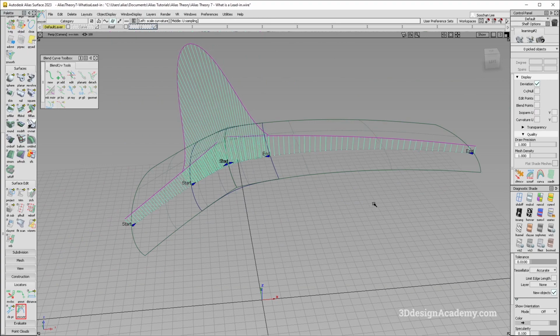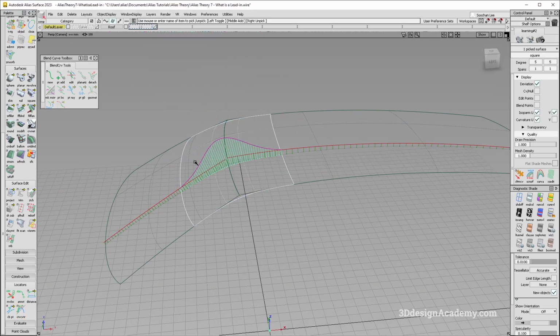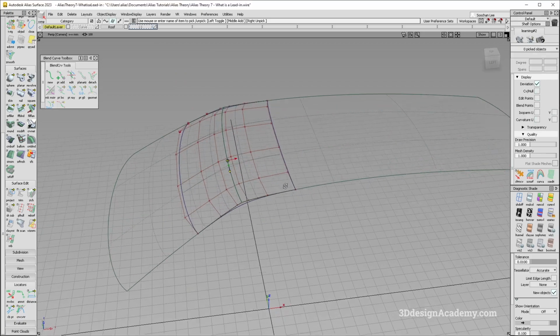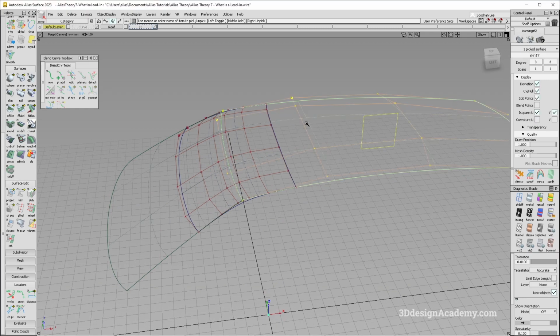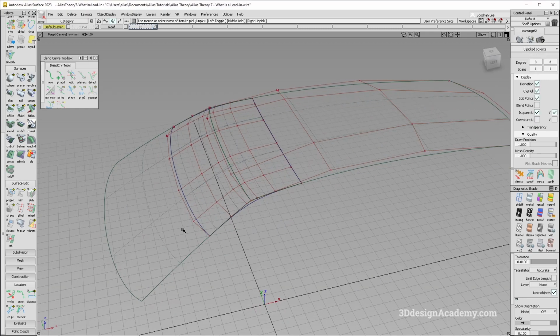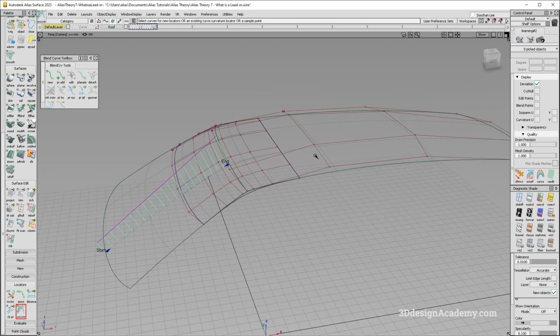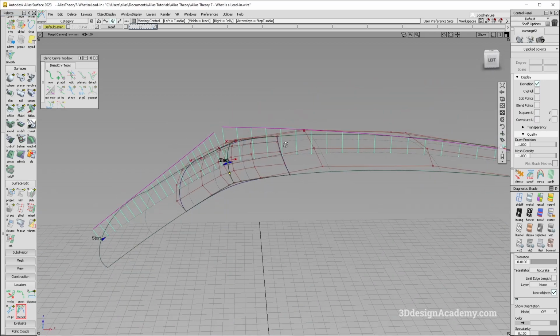Over here like that. Now, it's actually pretty smooth because this fillet over here has a lot of lead-in in the fillet itself. But what I'm going to do is make it a little bit better by giving acceleration towards the primary surface. Because if you were to just look at this, yes, there's a little bit of acceleration towards the end, but I don't think it's quite enough.